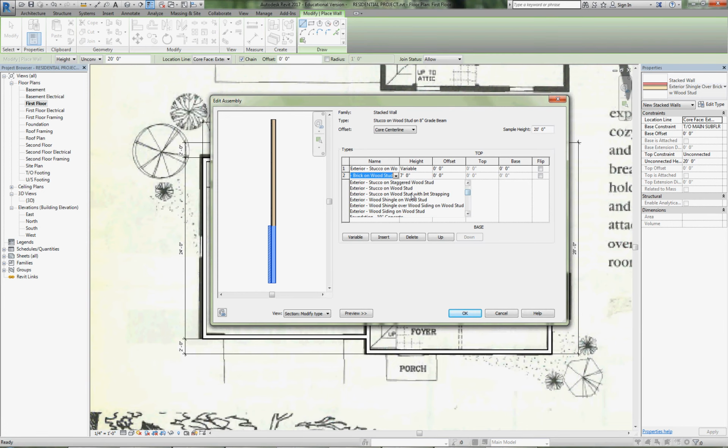So this is the same list as we saw over here on the wall types. So I'll just drag down and find my 8-inch concrete. Now the difference is here we can control the heights of these two components. Since a grade beam is typically always 2 feet high, we're going to set it at that. The garage wood wall height could be anything, so it's a variable wall height, and we're going to leave that as a type. This one has a height defined to it.